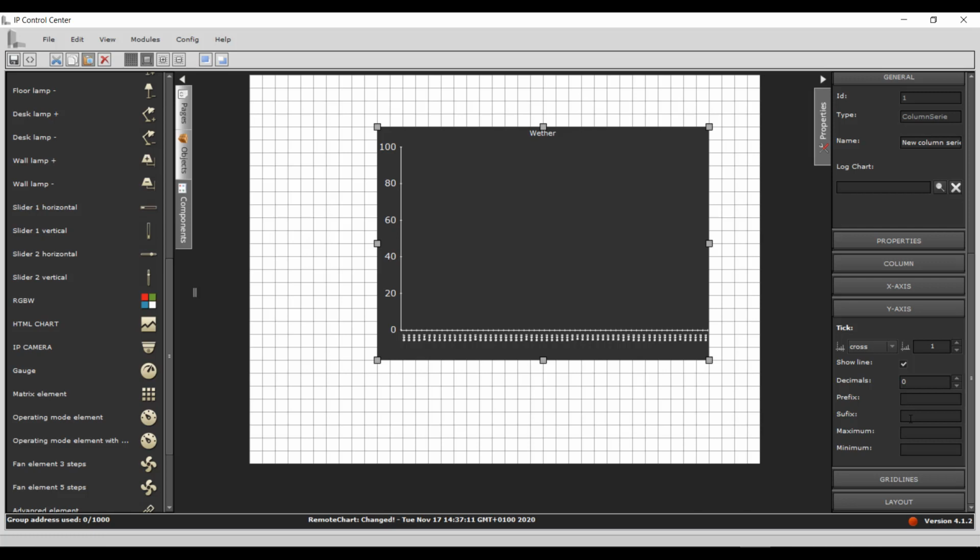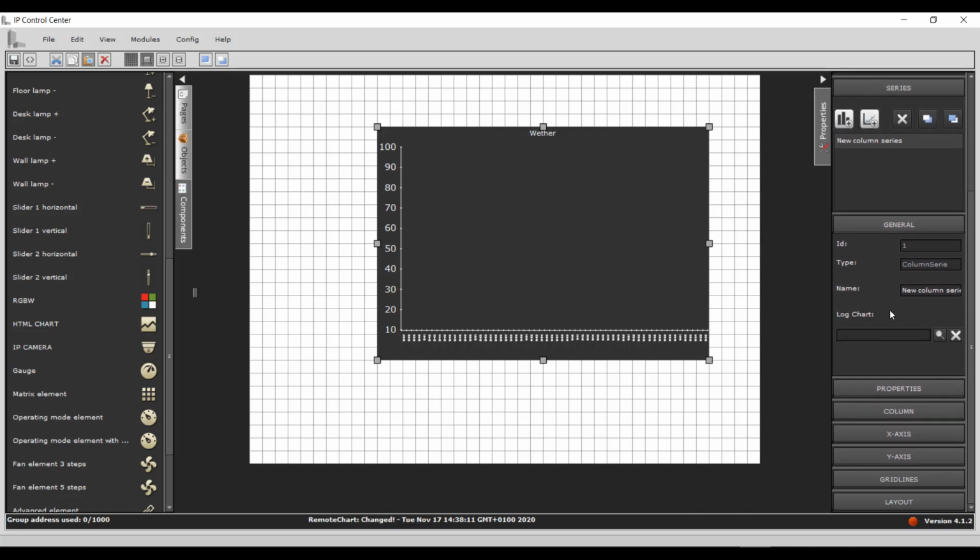Default. A time range can be preset for the display of the chart. Time ranges are available from 1 hour to 1 year. In the window Y-axis, the appearance of the Y-axis can be adjusted. Tick. The Y-axis is divided by small tick marks according to its value allocation.